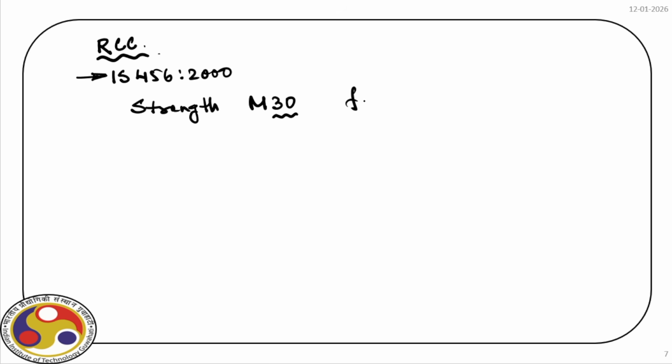Right. Now, this value is called the fck value. So, for M30 concrete, the fck, the characteristic strength of the concrete, is 30 Newton per millimeter square. Now, this is the strength that we get from the cube test. So, if we use the same concrete against flexure, we use this fcr value, which is 0.7 square root of fck. This is provided in this code.